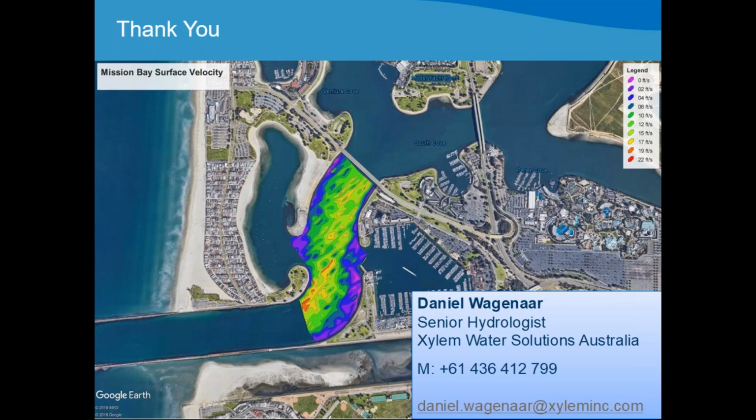in detail before making a decision. I can't indicate to you that the 16 would be enough or not enough. What I would recommend is perform an in-depth analysis using either Extrap or QRev and look at the velocity profile. If you see a bend back, that could be, but then again, you need to verify if there was no wind blowing upstream as well, and the aspect ratio, if that is applicable or not. So there are certain factors that you need to evaluate before you make a decision. So it's very difficult to give you a single answer on this, because you need to evaluate all the different factors involved.